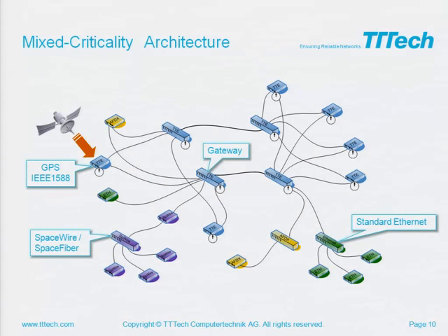If we have established this synchronization, it's then possible to synchronize it to different absolute clocks. So here we are talking about a relative synchronization, and it's possible to now synchronize this relative synchronization to an absolute time. This means you have, for example, GPS, an absolute time base, and then every communication participant in the network would see the GPS time.